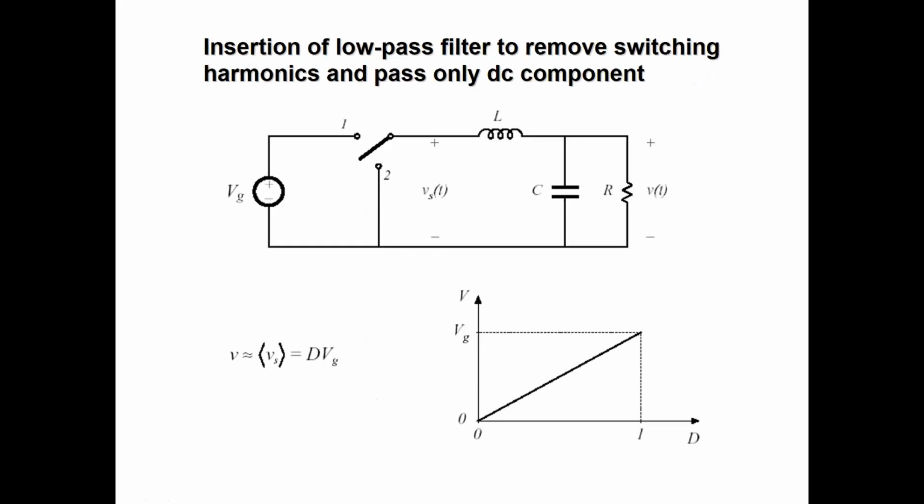Now this is a step down converter, a DC to DC converter. We have already studied that due to the switching changes, some ripples arise in the circuit. If we want to eliminate these ripples, we have to install a low pass filter consisting of an inductor and capacitor. These ripples will be eliminated through these filters, and the load will receive a favored DC voltage.